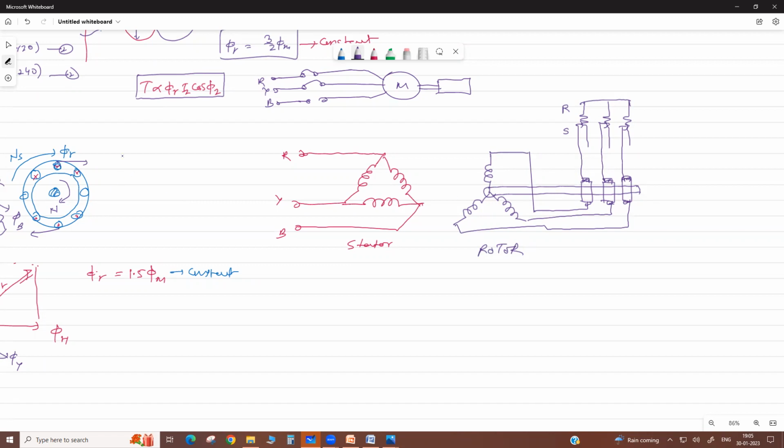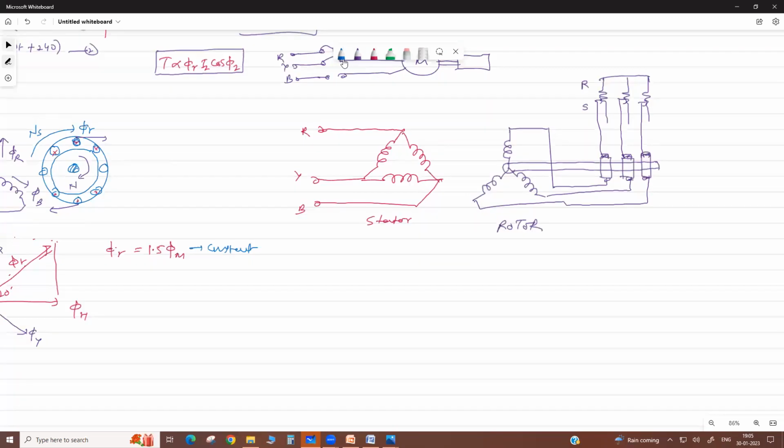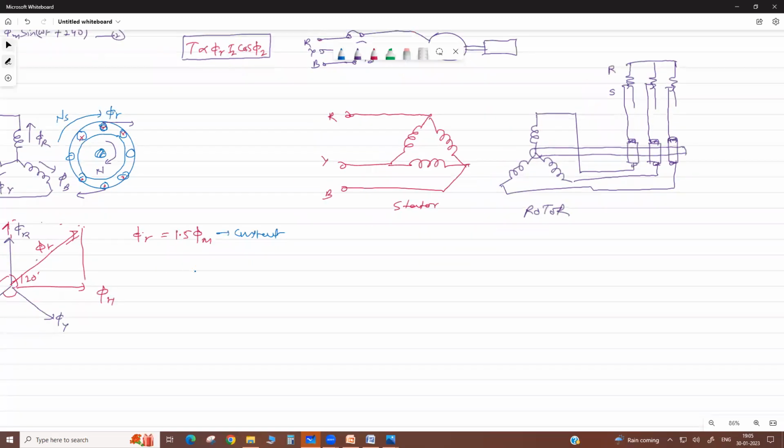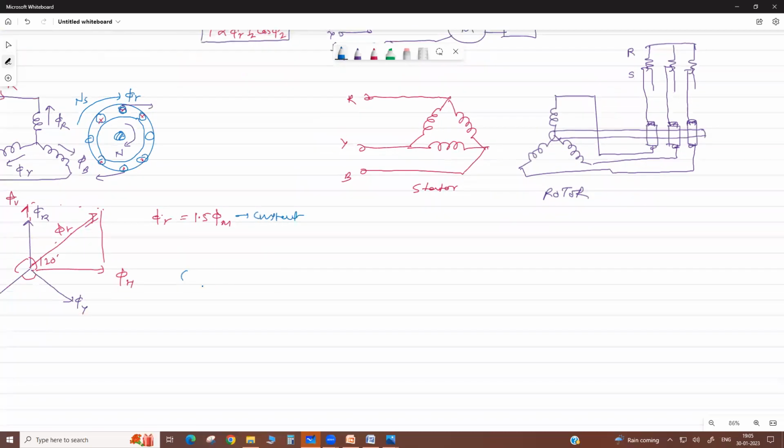Correct. Now, what is the comparison here? I will explain in simple words. Here, the rotor conductors are bars, like thick bars. Their length is short and the cross-section area is large. Then resistance R2 is L by A, so if length is short and area is large, then resistance is low. That's why this squirrel cage has a low resistance.